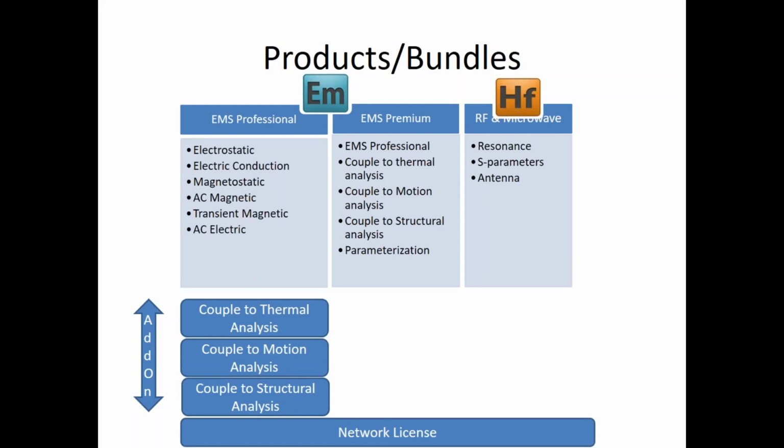feature inside EMS, where you can tie the geometry parameters in SolidWorks like dimensions, etc., and now you can simulate over a range of those values to see how it behaves. For example, if you're not certain about what the sizes of these magnets are, you can actually tie the dimension in SolidWorks as a parameter, and you can use it to iterate and understand how the variation of dimension varies the field, the strength of the field, as well as distribution.